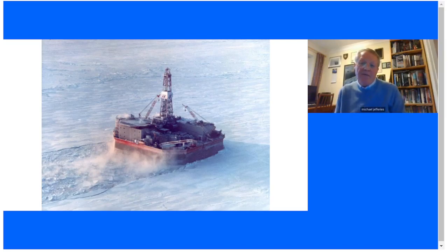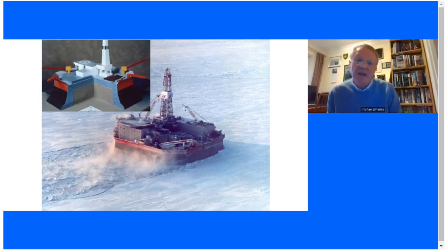And now this is not a very badly designed ship going from left to right. This is the Gulf exploration platform, the Molikpaq. And she's sitting on the seabed, and that is ice flowing past her. This is quite early on in the winter. And the ice you're looking at there is about 0.5 meter thick. And that's by no means as thick as the ice gets. The Molikpaq is actually designed to resist 5 meters of ice pushing against the rig. How did we achieve that capability? Well, the answer is shown in the inset here.